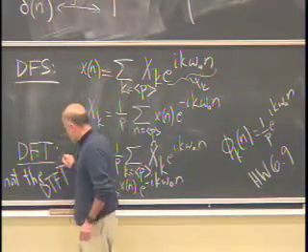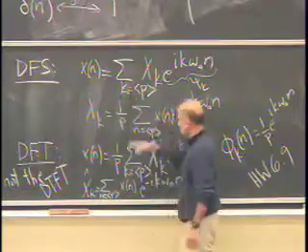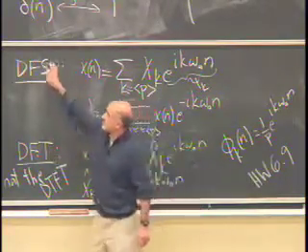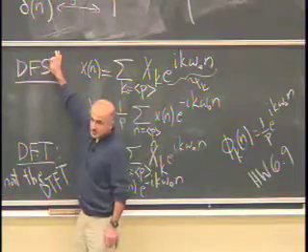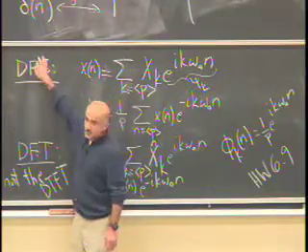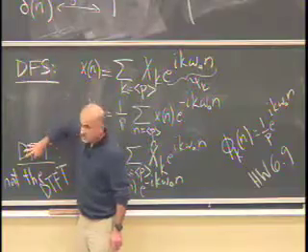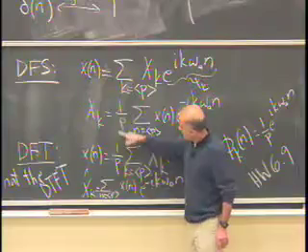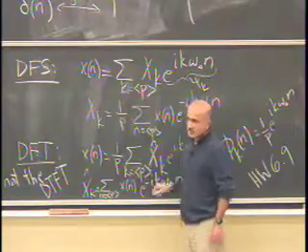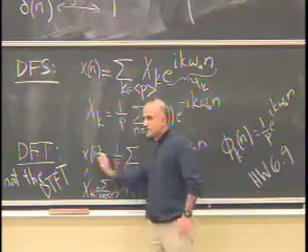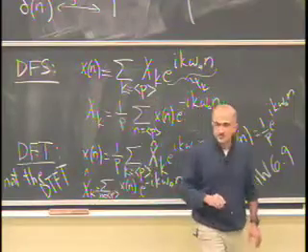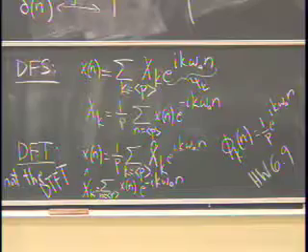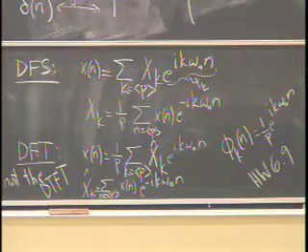And the only reason this came up is that somebody asked me where the constant goes. If you replace everything we said for discrete time periodic signals, where we discussed the DFS, with this one, which is just the altered form of that, then the 1 over p moves from the analysis to the synthesis equation. That's it. But I don't really want you to get fixated on this. Just have it in your formula sheet. We'll give it to you in a table. And remember, for the midterm, you get to bring 3 sheets.